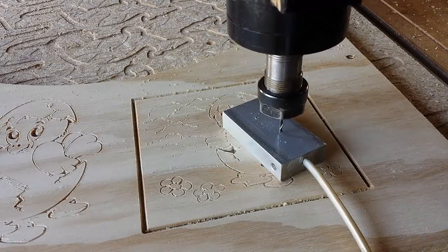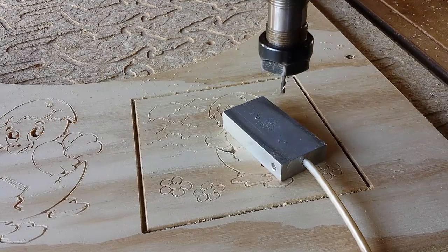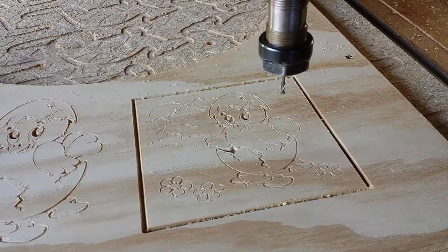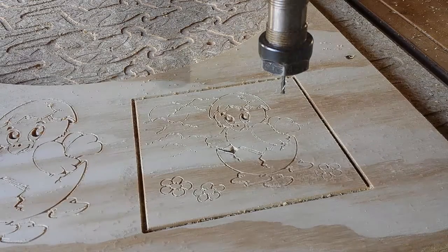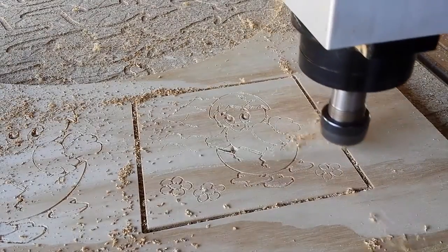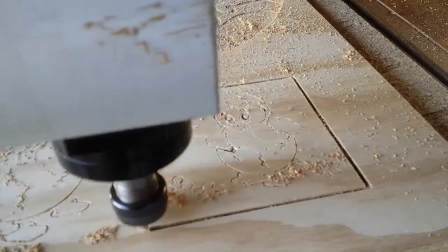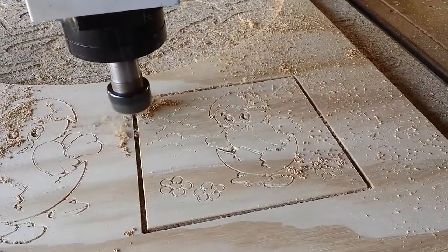We are now ready for the final cutout, and this requires a change in the cutter bit. For the cutout path we use a 3mm bit with a flat tip, cutting to a depth of 12mm, which is the thickness of the plywood used for the job. On the final pass we can see that the router is adjusting for the tabs that hold the job in place during the final cut.